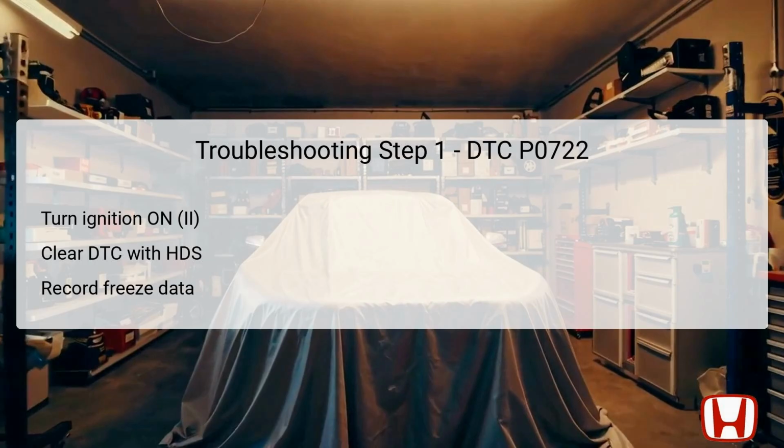This data can include vehicle speed, engine load, and other pertinent parameters at the time the DTC was set. Analyzing this information will provide better insights into why the fault occurred and help in subsequent troubleshooting steps. Recording freeze data is essential as it helps establish a baseline for further diagnostics.